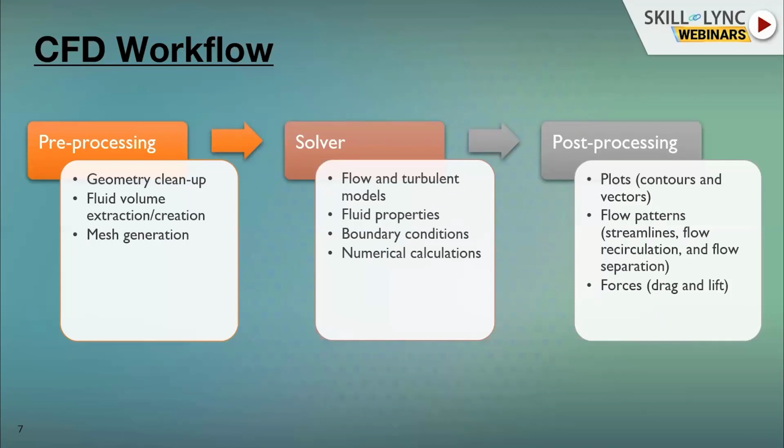Pre-processing involves, from the designer, one may receive the geometry, then he needs to know what is required for his CFD problem. Those domains he has to extract, clean up other things. Then he has to extract the fluid volume. He has to define the inlet, outlet, or other boundaries.